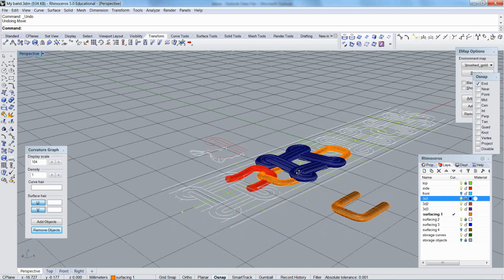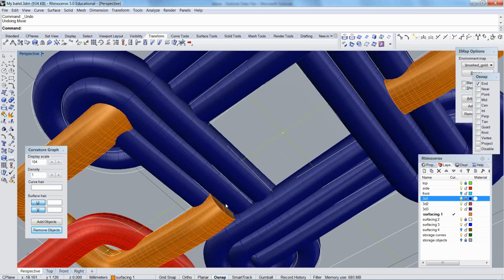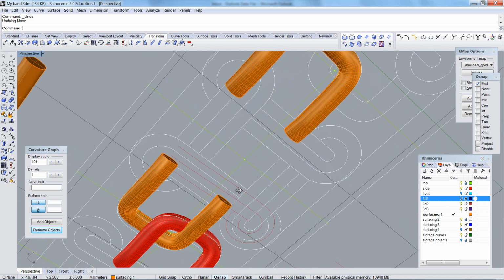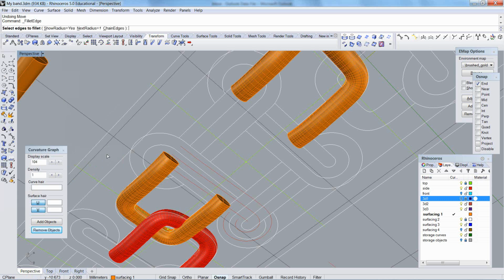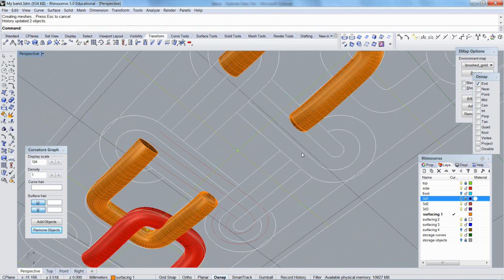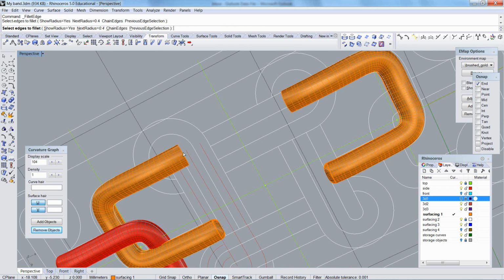So as a maquette, I would know that in my finished piece I don't care for this. I would change some things in my finished design. For now, I could just come in here and fillet the edge. It's a 1.2 maximum, so 0.5 fillet. Too much. 0.4. It's actually probably going to still be too much. No, that worked. And I can notice how it updated the other ones automatically.